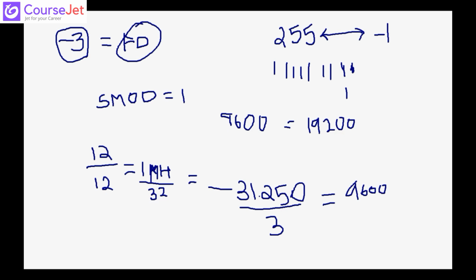Once you load and start transmission, SBUF will transmit 1 bit by 1 bit. Once it is done with transmission, your SBUF becomes empty. Once it becomes empty, you have one bit called TI, the transmit interrupt flag, which will be set. So we will wait here till TI, whose default value is 0.